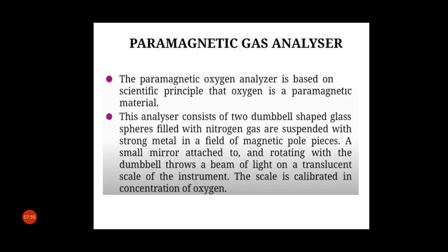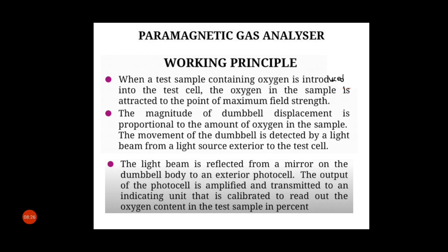This analyzer consists of two dumbbell-shaped glass spheres filled with nitrogen gas, suspended with a strong metal in a field of magnetic pole pieces. A small mirror attached to and rotating with the dumbbell throws a beam of light on a translucent scale of the instrument, and the scale is calibrated in concentration of oxygen.